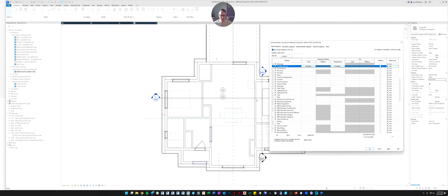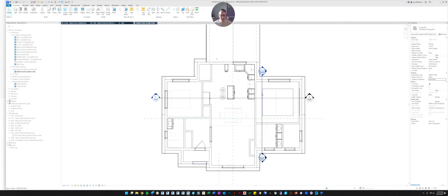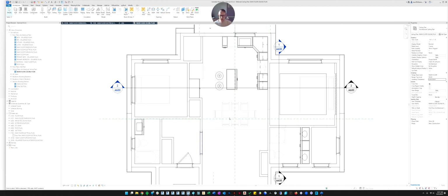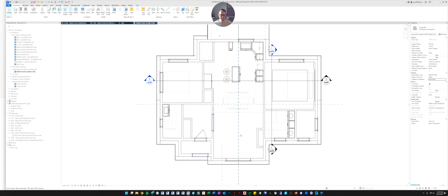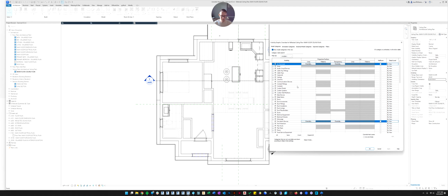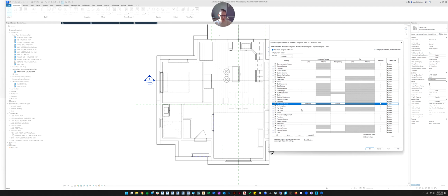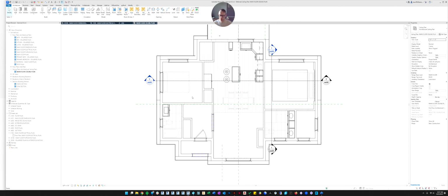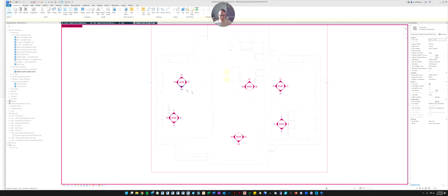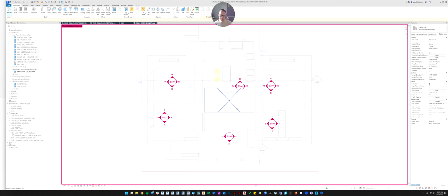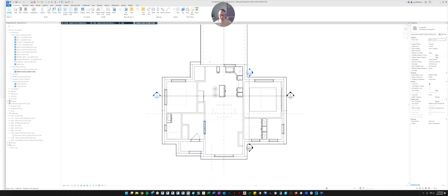It shows that it's on, but my table isn't showing. So now my casework is showing. I don't know why my table isn't. And same with my couches. Couches are definitely furniture, so that's not the problem. Let's go down to this little button that's called Reveal Hidden Elements. Let's click that light bulb and see. Anything in red means it's hidden in the view, but it doesn't show that my furniture is hidden. So something else is happening here.